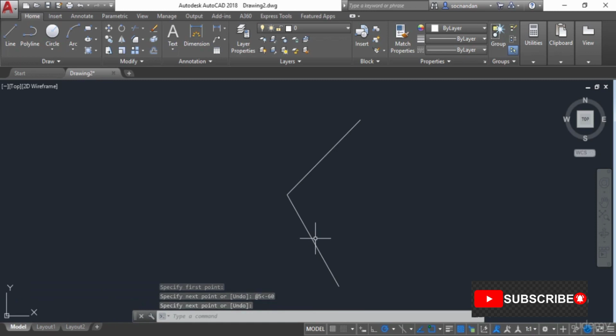You can also use a positive value, or you can also use 300 degrees for making the same line. So that will be 180 degrees plus the additional angle, that will make 120 degrees here, and that will be this minus 60 degrees angle. So this was all about using different distance entry methods in AutoCAD and making a line with that. And from the next lesson, we'll start making some of the other simple geometries in AutoCAD.